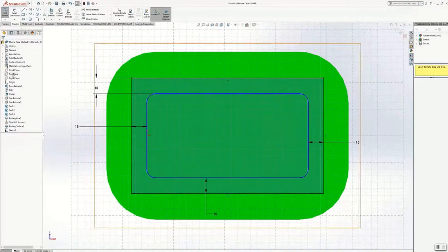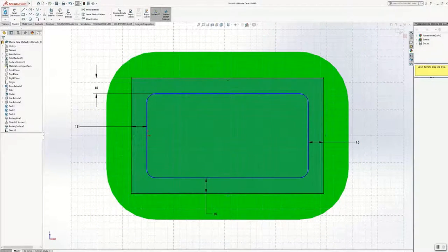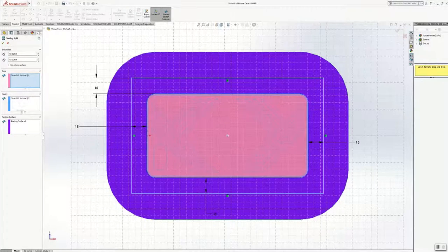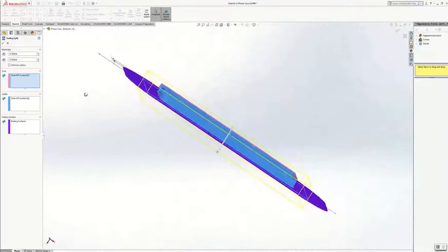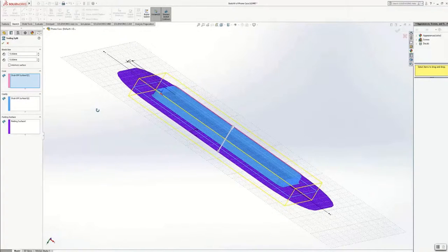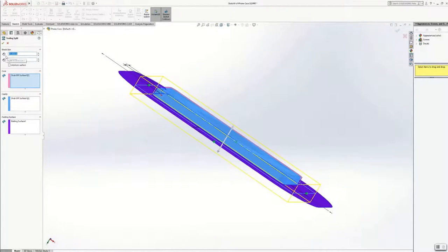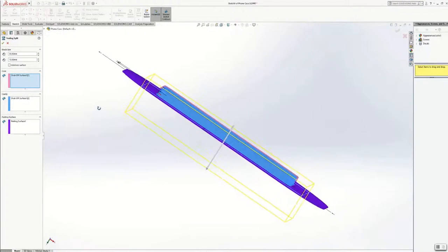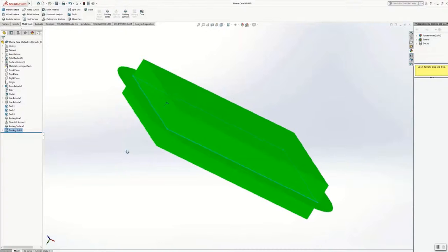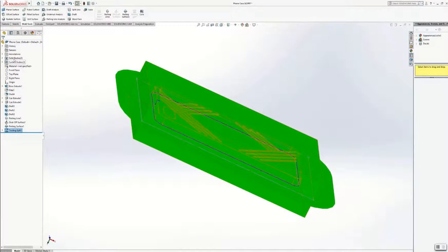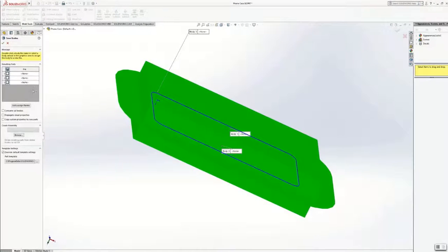Now once you exit the sketch, we will choose a block size. Once we press OK, we now have the 3 different parts. We can save these individual parts by looking at our model tree and right-clicking on the folder Solid Bodies and choosing Save Bodies.